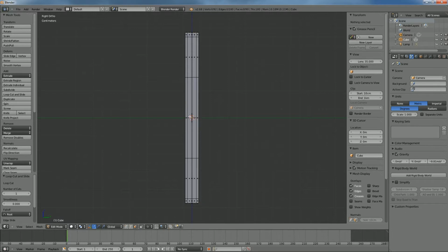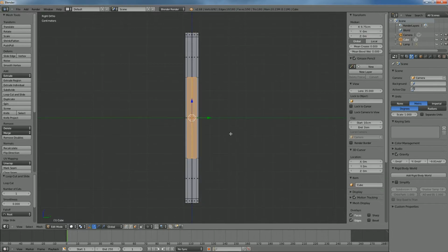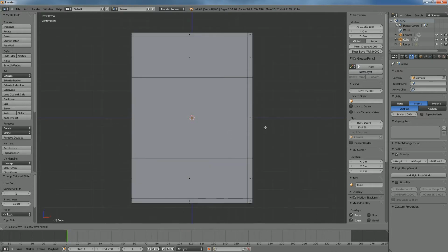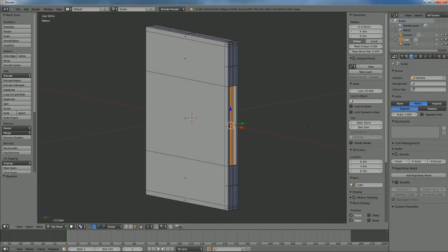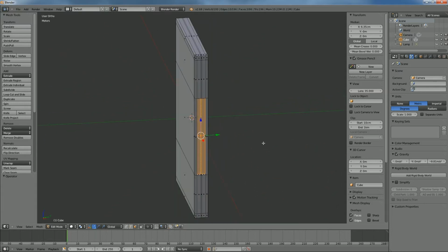And so now we just have to extrude the finger area back. So we're going to select these 3 faces here, and we'll go to the front, and I'll press E, right click, and we'll move this back on the Z to, since it's 4 millimeters back, we'll go 6.35 millimeters. And that doesn't seem right. 6.35 centimeters. That's right.